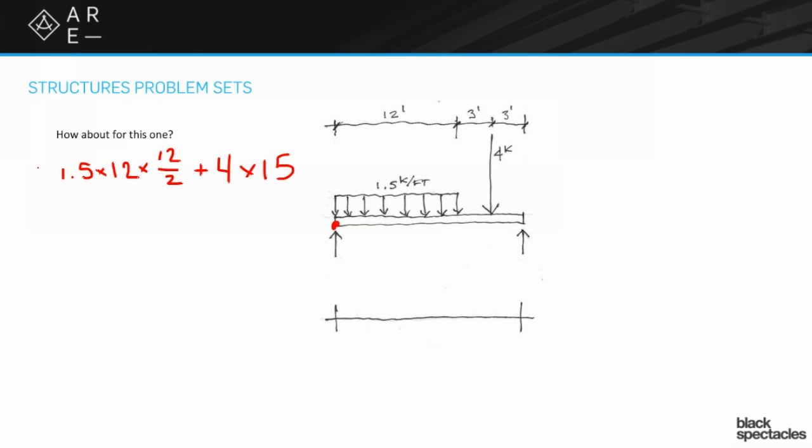And when we do this, all of this has to sum up to 0, because otherwise we don't have a static beam here. You don't want your beam galloping down the road. Yes, flipping around. So I'm going to call this other end here B, just to give us a value. But it is acting in the opposite direction that the other 2 loads are. So it's going to have a minus sign. And it is acting at, let's see, that's 6 and 12. That's 18 feet. And when you solve for B, it actually comes up to